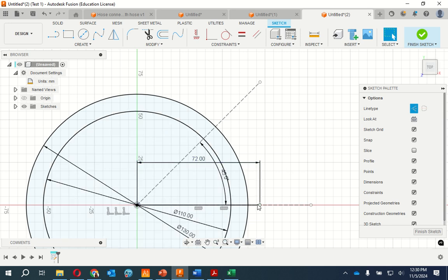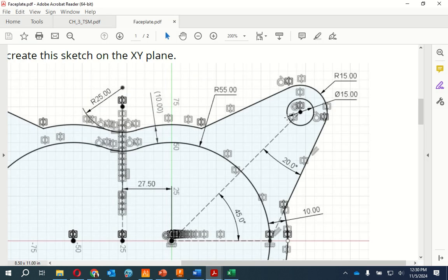So I'm going to get rid of this line too. I don't know how I did that one. There we go. So I have my line. There's my point right there, and I'm going to make my circles from this one here. So this one says the diameter, that's arrow to arrow, is 15, and the outside one has a radius of 15. So that means that the outside has a diameter of 30. So I'm going to do my two circles now.